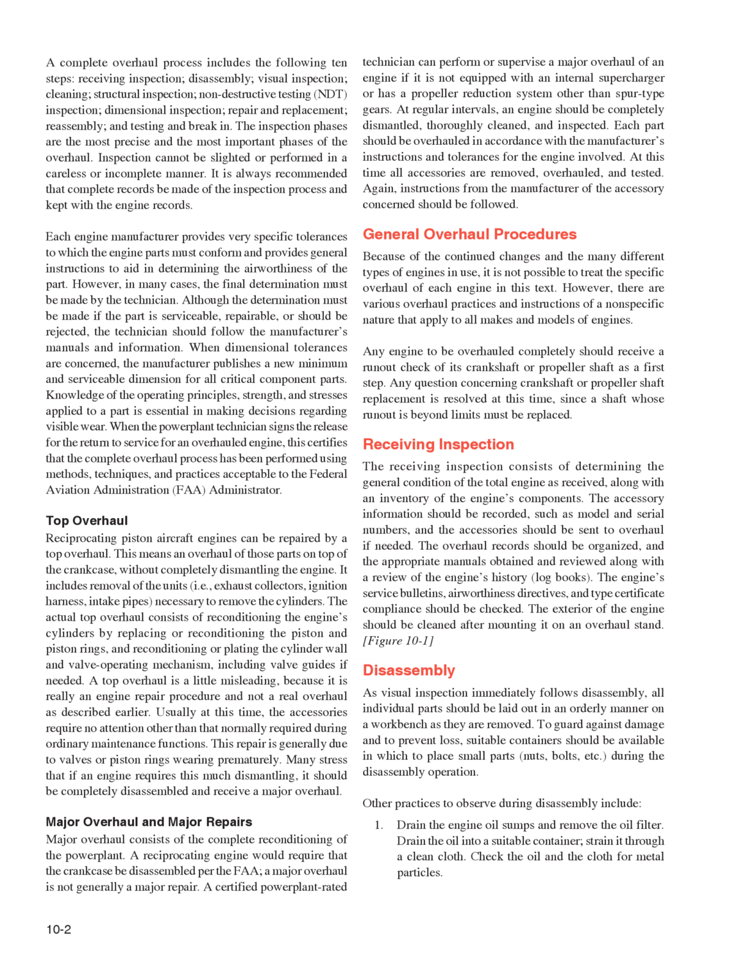The inspection phases are the most precise and the most important phases of the overhaul. Inspection cannot be slighted or performed in a careless or incomplete manner. It is always recommended that complete records be made of the inspection process and kept with the engine records. Each engine manufacturer provides very specific tolerances to which the engine parts must conform and provides general instructions to aid in determining the airworthiness of the part. However, in many cases, the final determination must be made by the technician.